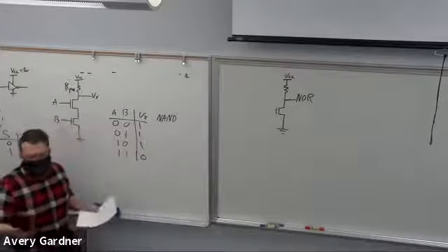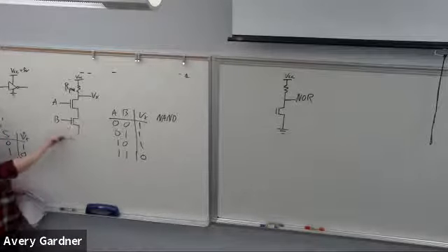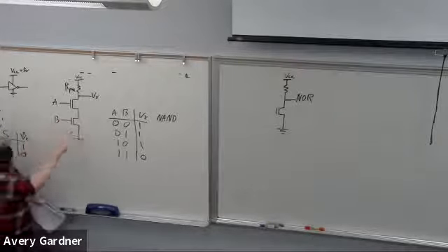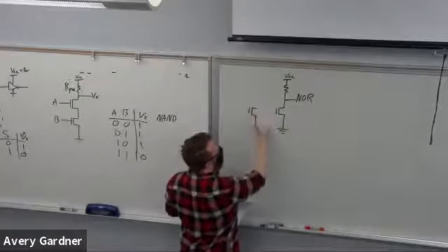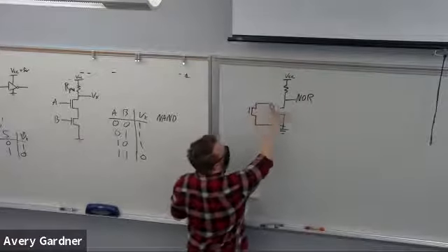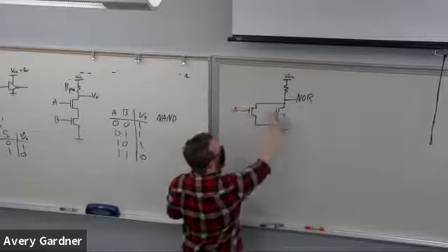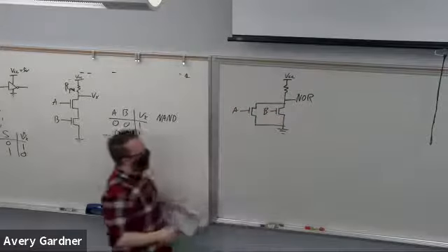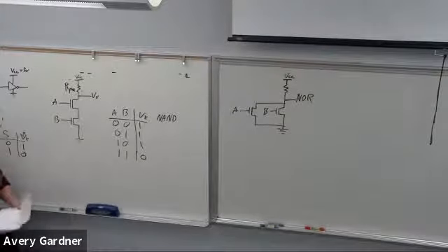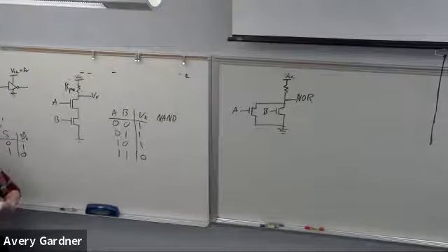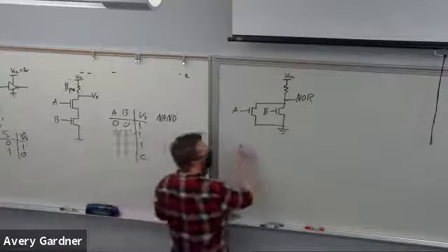What that means is we'll just put them in parallel. Remember the vocabulary? These guys are in series. We're going to put 2 gates in parallel instead. Now if either A or B or both are switched on, closed, it goes to ground. Remembering that our truth table for the NOR gate